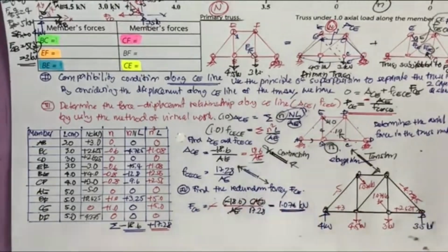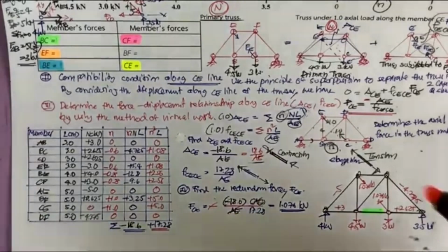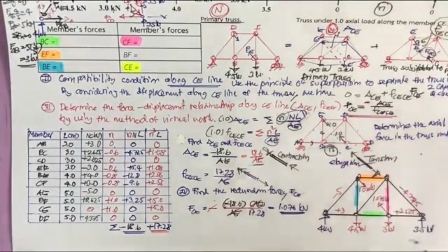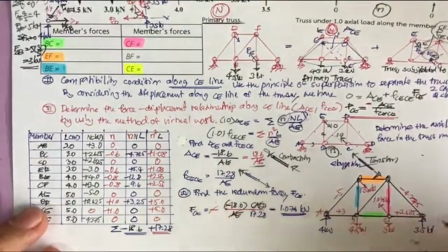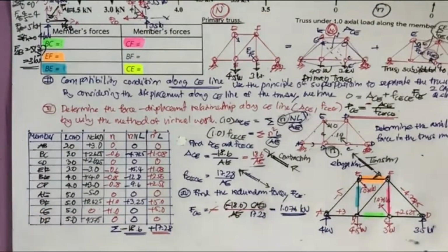Okay, now what you guys are going to do is determine the force in this member, in this member, in this member, and in this member, and then you can answer this, right? As it's going to be A, B, C, D, E, F. You do it by using the same method of section or method of joints. Mostly you're supposed to use method of joints.